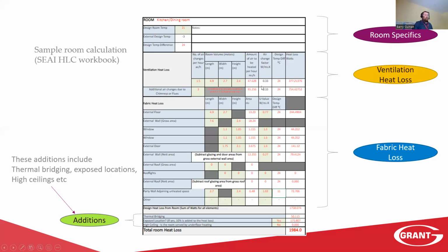By increasing the air tightness of the room, and this is in simple terms, if there was an air tightness test done on the building and we could get it down below 5 air changes, which would bring it in line with building regulations for new buildings, then we could use the new build air change rates. So this would go from 1.5 to 0.5.